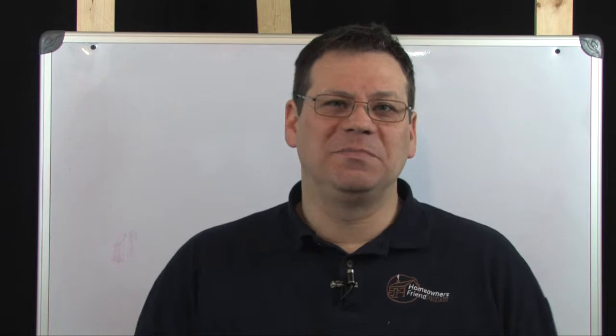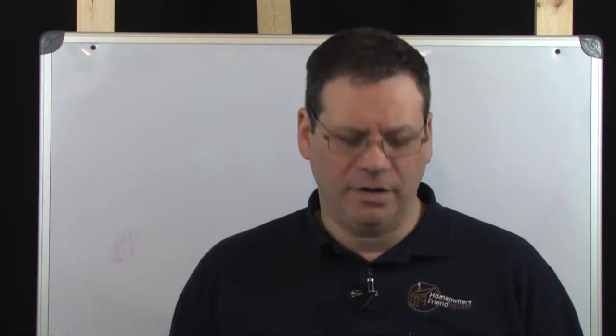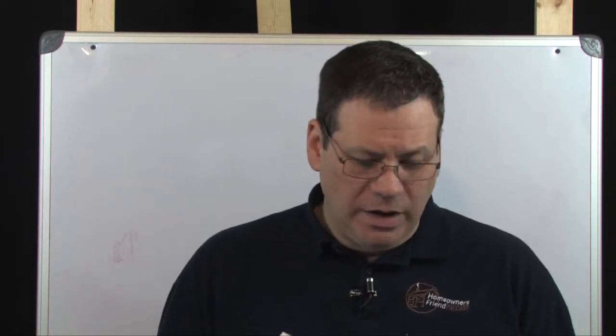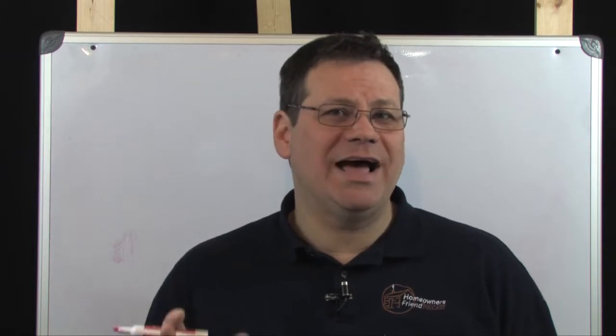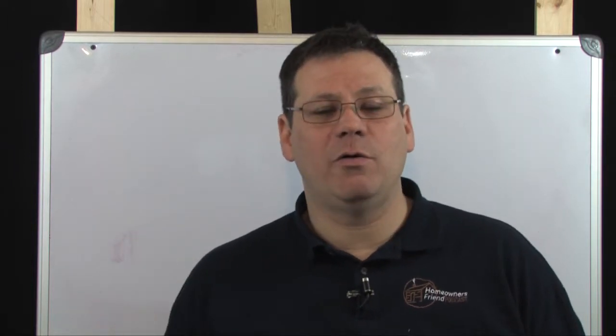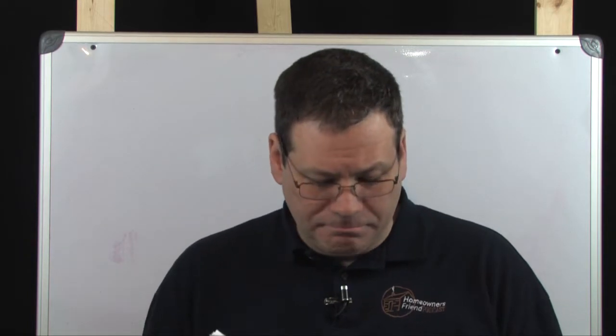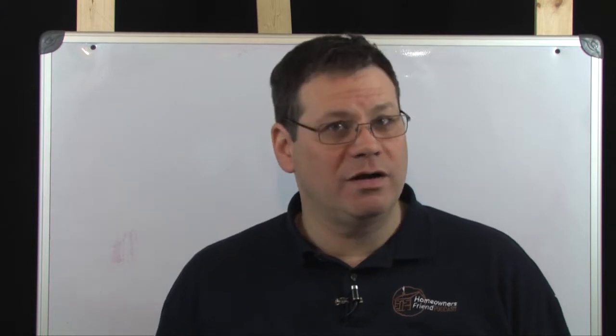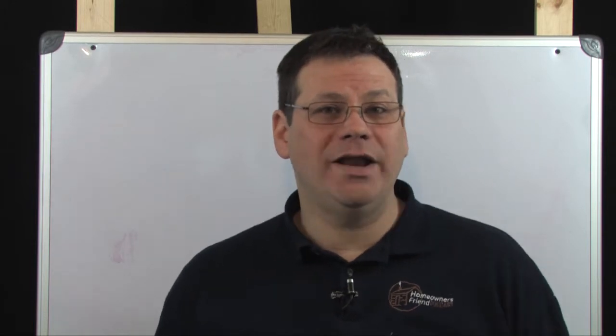But I'll ask you a question now, if you're so smart. What uses more power, a 1,500 watt electric heater, or a 60 watt light bulb? Now, I know a lot of you jumped in your mind and said, well, of course, the heater. And you could be right, but I can show you how you can be wrong. Because we have to introduce a time element whenever we're talking about power and how much power we're using. In fact, time can be as important or even more important when figuring how much power something uses than the actual wattage rating of it.